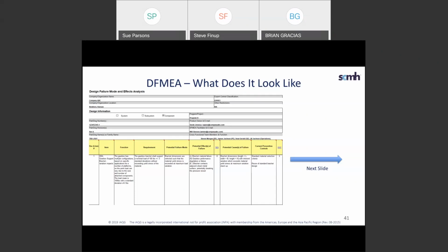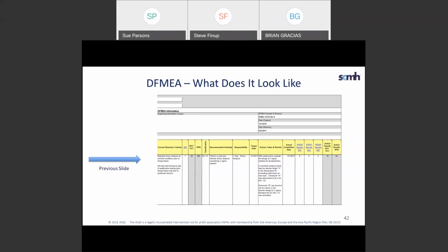Following is a statement. The critical elements of a design should be reflected in severity rating and reflected within the RPN. Correct. Okay. RPNs may be used to prioritize risk for action to reduce overall risk as part of their continuous improvement activity.